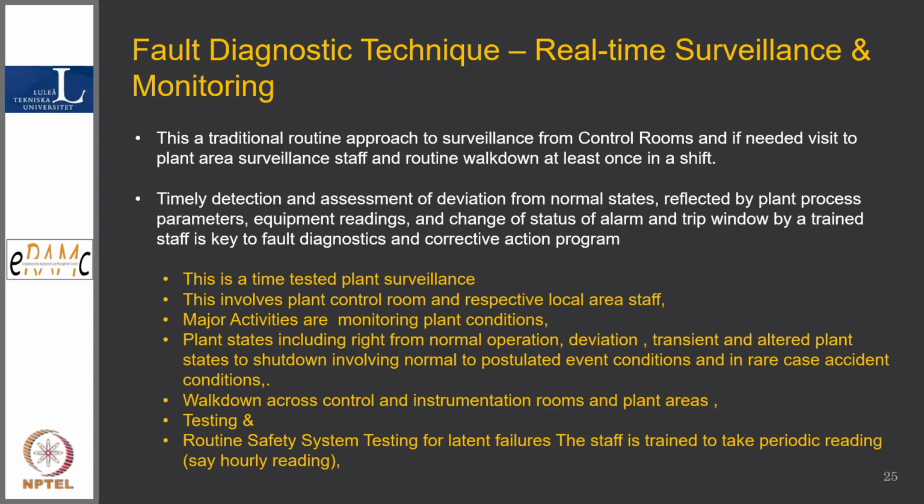Even if I put some instrumentation in the site, it is easier for local staff to go and hear the noise and get a sense of it, why the temperature is going up, why vibrations are seen today which were not the case before. That first hand information is communicated to the control room, and the control room will talk to the respective agency or people, whether it is working hours or odd hours, and that whole procedure starts the corrective action program. Here the major activities are monitoring in the plant control room and corrective action.